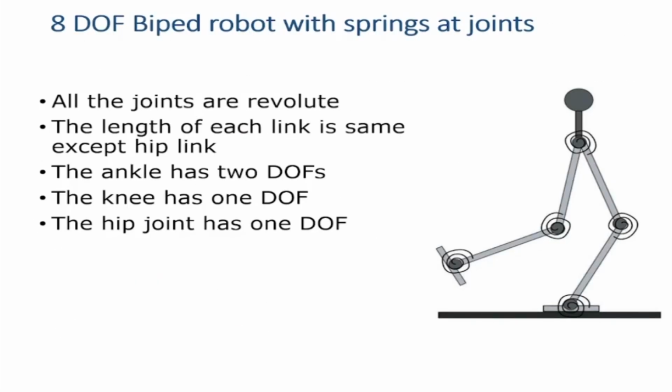Several robots have been tried. So this is another design of a robot. We'll show you some of them. In this design, a spring was added at the joint. So there is a motor, and the motor output goes through a spring, and then to the link like this. So I'm adding some stiffness in there, and that is what essentially gives the stiffness at the joint.